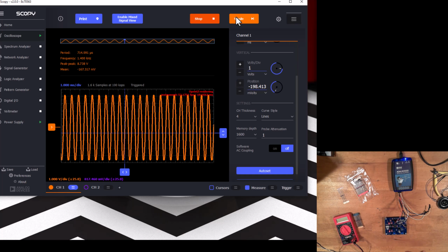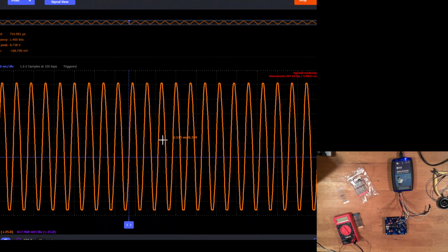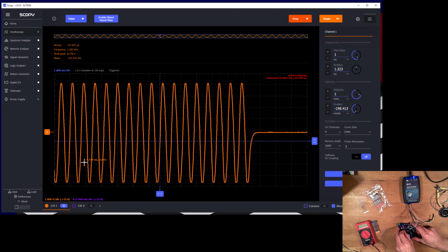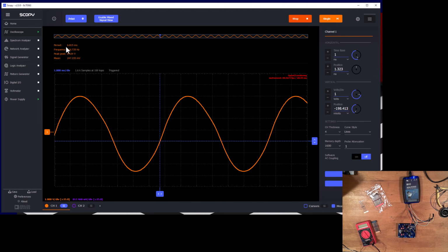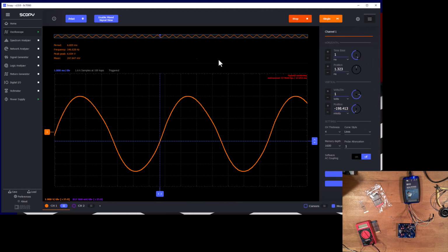So let's take a look at the scope shot a little more detail, and I'll make this a bit bigger here. What do we notice? Well, we notice that we are visibly clipping a little bit, and I'm going to set us back into the center range so that we can get a frequency of about 1 kilohertz. Okay, so I've got the measurement feature turned on here. I can enable measurements of the sine wave here. Okay, great. So you notice I've got a frequency of 146 hertz, peak-to-peak value of about 6 volts here. I've got some visible distortion in here, which is not unexpected.